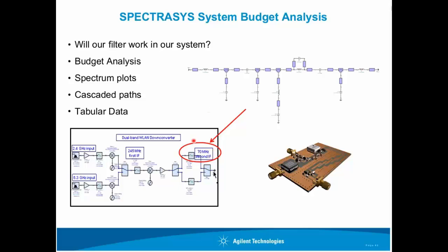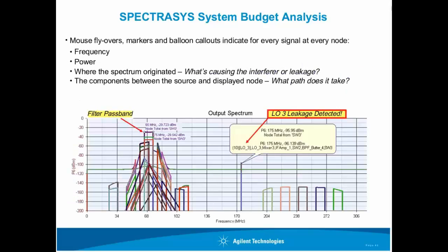And typically the system architecture is created first, and the filter parameters flow down from the system requirements. We usually use behavioral models, as shown here, to determine the system performance. And then after we've completed the filter design, we can substitute it in at the system level and determine that we're still meeting our system specs.